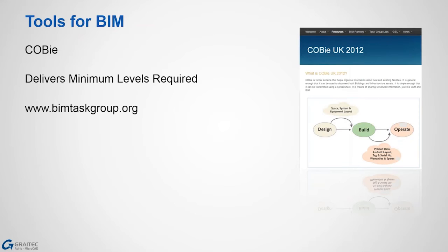Autodesk also have embraced the COBie approach and to help us deliver a BIM package, a toolkit for Revit that provides a data exchange protocol that conforms to COBie. So we have actually got a plugin, I mentioned that before, and with the COBie plugin, it will enable you to produce the minimum level of detail to achieve BIM level 2 as required for government funded projects by March 2016. So look out for the COBie toolkit for Revit.